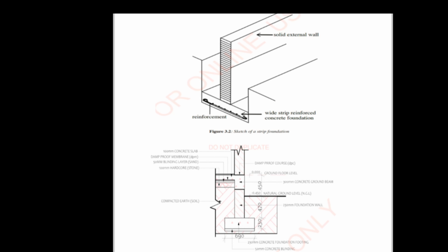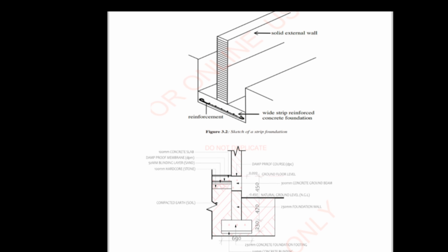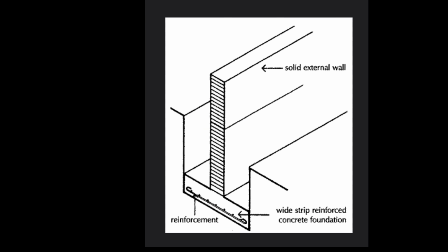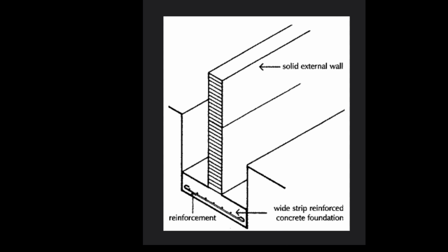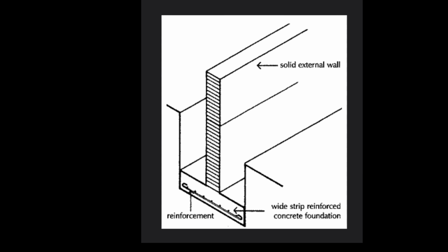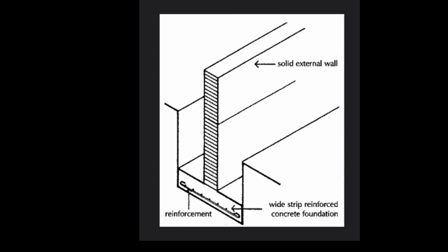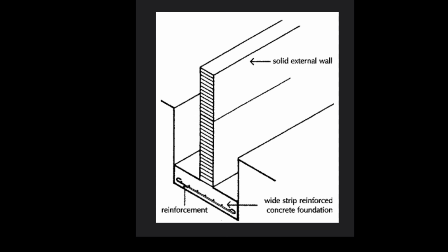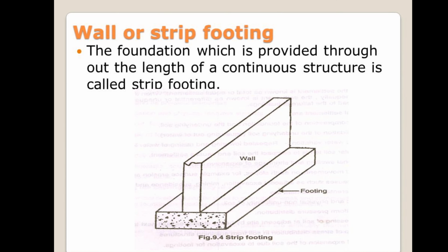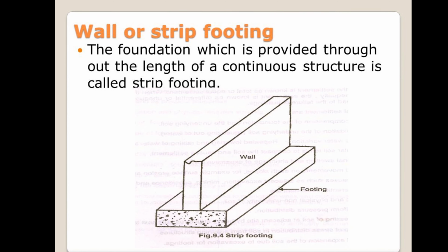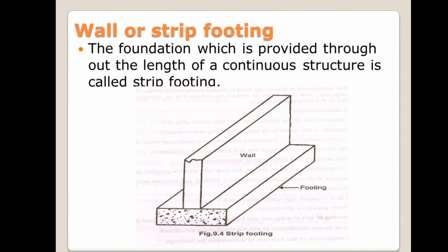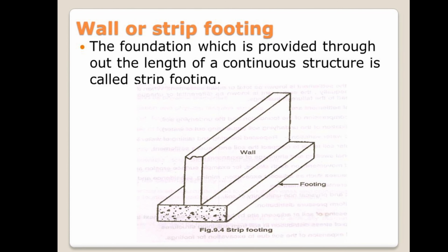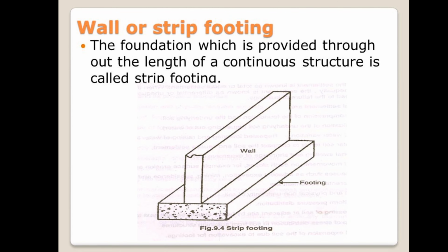Strip foundation. These are types of shallow foundations suitable for stable subsoil and small building loadings. They are mostly used in low to medium rise buildings. Strip foundation can be made up of concrete, blocks, stones, or steel. A strip foundation is advised when the building has load-bearing walls, the soil has good bearing capacity, it works well on firm soil like gravel and sand, the structure is relatively lightweight, used in residential and small commercial buildings, and the load is spread out evenly, suitable for buildings with uniform load distribution.